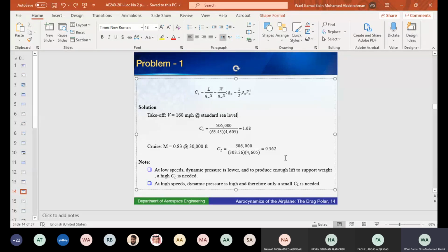We already know this. Yeah, the point here is that I want you to develop a sense of the numbers that we have. Because in design, we will go the other way around. In this problem, I gave you the wing area of the aircraft and we were calculating what CL. But when we are talking design, it has to be the other way around. Remember, when you design, that means you don't have that thing physical. I don't know what's the wing area.